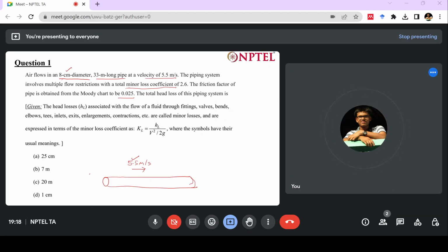So it will be a delta P. We can also simply use a length dimension by just dividing by rho. Now, what we are interested in is how much head loss has taken place. If I am giving a head of delta p by rho g on the left side, and the flow is taken from left to right, at the right side there will be a reduction in head.